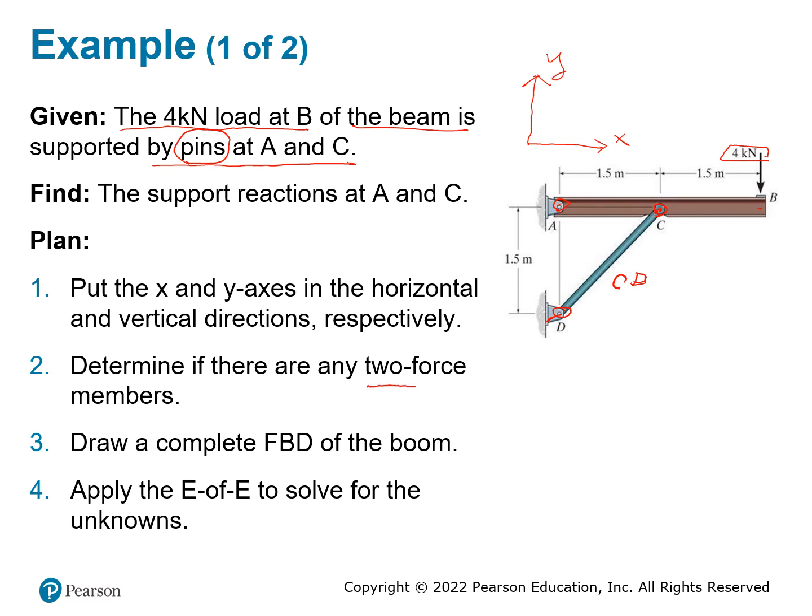And we just show you what is the 2-force member, right? So the 2-force member is going to be the CD, C and D is a 2-force member. Then you're going to draw a free body diagram on this bar AB. Then we can apply the equilibrium equation to solve the problem.